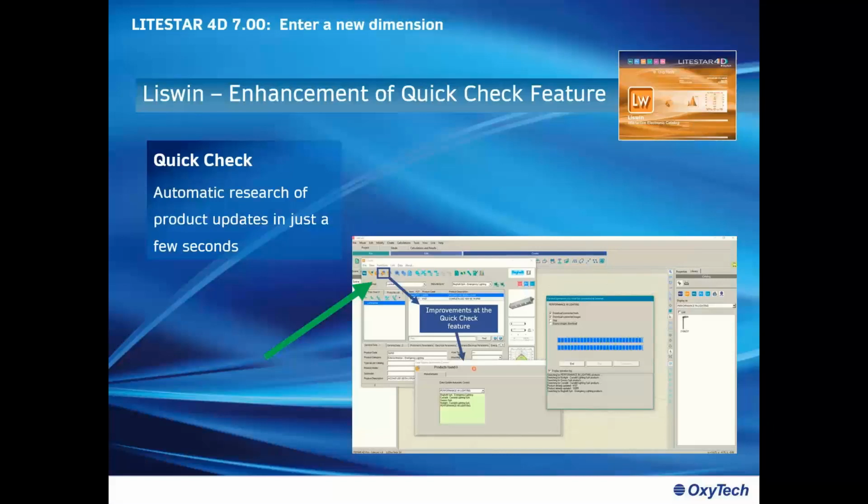So in this aspect, we also introduced last year, and some enhancements were also included with this new version, the function managed through the OXL file, through which you can manage the luminaire driving current. So it means that you can have a single file and that's it.